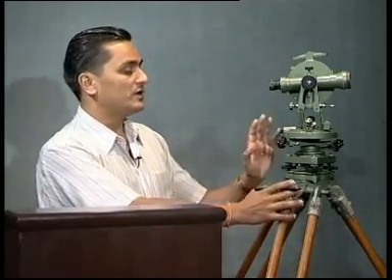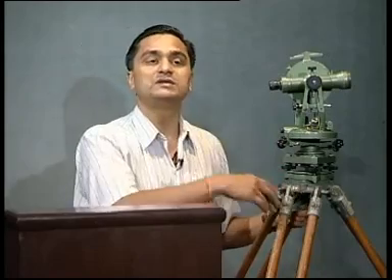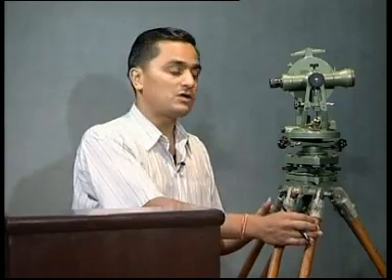How do we measure this? Using the theodolite. So this is what we are going to see now with the help of the theodolite. Now here in the theodolite, some of the procedures are the same as in the case of the horizontal angle. First of all, we take this theodolite to a point where we need to measure the angle, because obviously whenever we are measuring the angles, we are measuring them at the point of the observer, some station. So we will take this tripod there, we will center it, we will level it.